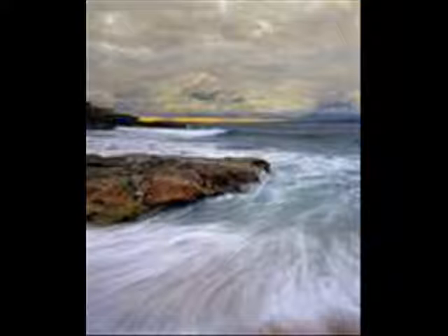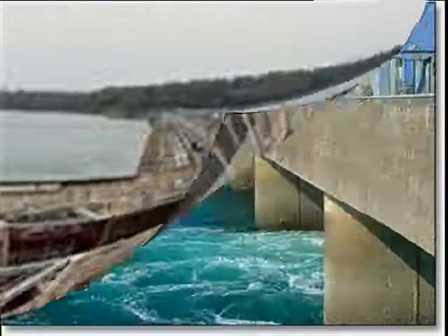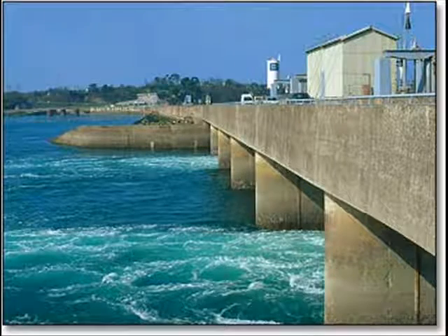What are the costs of tidal power? Tidal power is a form of low-head hydroelectricity and uses familiar low-head hydroelectric generating equipment, such as has been in use for more than 120 years. The technology required for tidal power is well developed, and the main barrier to increased use of the tide is that of construction cost. There is a high capital cost for a tidal energy project, with possibly a 10-year construction period. Therefore, the electricity cost is very sensitive to the discount rate.